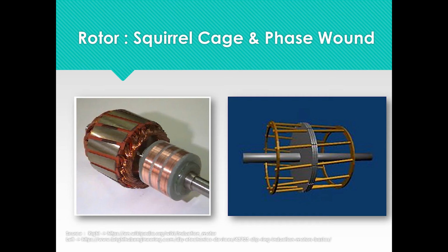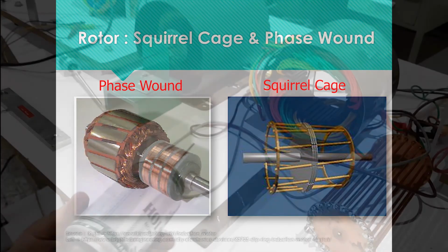There are two types of rotors for the three-phase induction machine as shown in these figures: squirrel cage and phase wound. Squirrel cage has several metal bars that are parallel and shorted. Current will go through these bars. Phase wound rotor has three-phase coils that are connected to slip rings with star connection. Loads can be added to these coils via slip rings to have better motor starting.